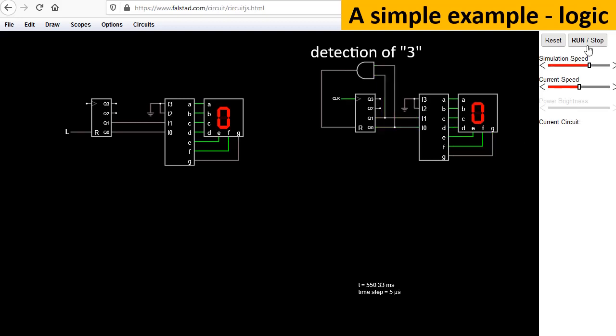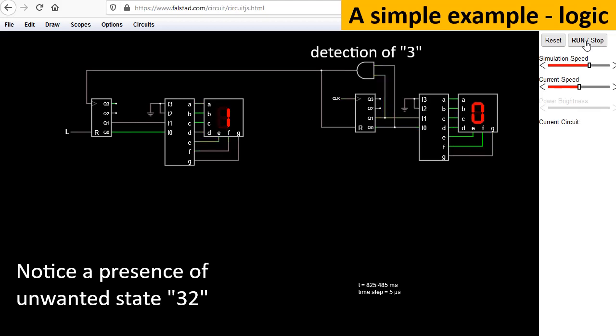So now we know that to reset this counter, we need to multiply those 2 bits. Good. Now, that signal would also trigger the next stage. So if we want to reset both counters immediately when 3, 2 arrives, that means that here we have to detect 3 and here to detect 2, which is just most significant bit.